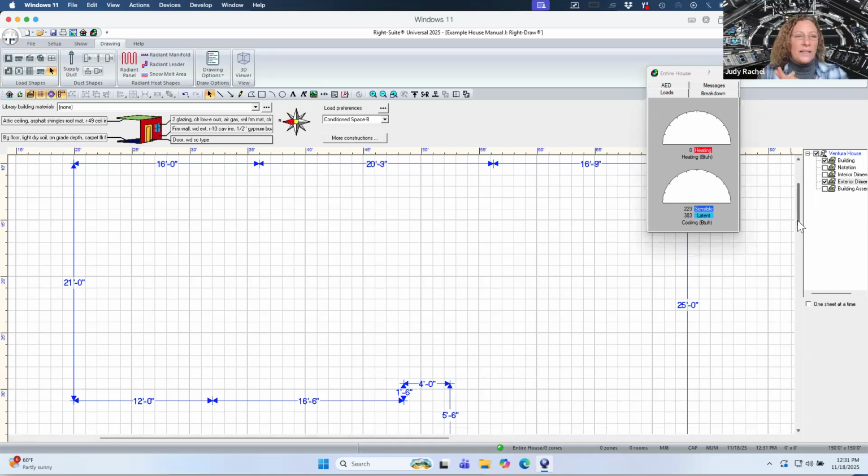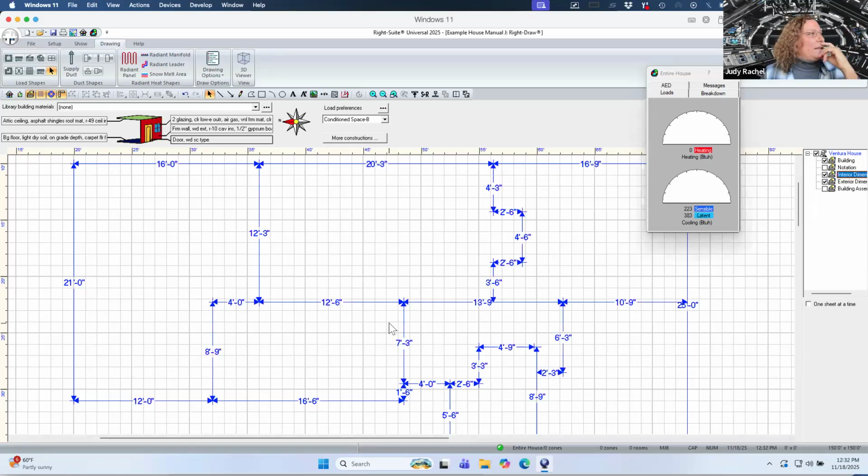People are scanning the houses from the inside. And if you do that, you need to do the math to figure out how thick is that wall, and you should be adding that measurement to what you put in your load calculation, because what we're actually measuring is the entire enclosure from the exterior. So here's the exterior measurements. Then I go inside the house and I start doing measurements and now I can start drawing the building. So I wouldn't normally have all these interior measurements, but I have them here for you so that I can get through this fairly quickly.